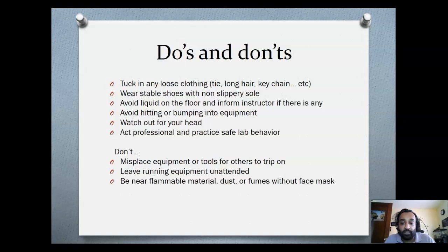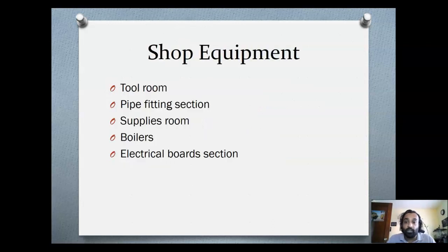Do not be near flammable material like dust or fumes without a face mask. So we have flammable material. Don't be around diesel or refrigerant or dust if we do cleaning, or any fumes without a face mask. Make sure you always have your face mask on.